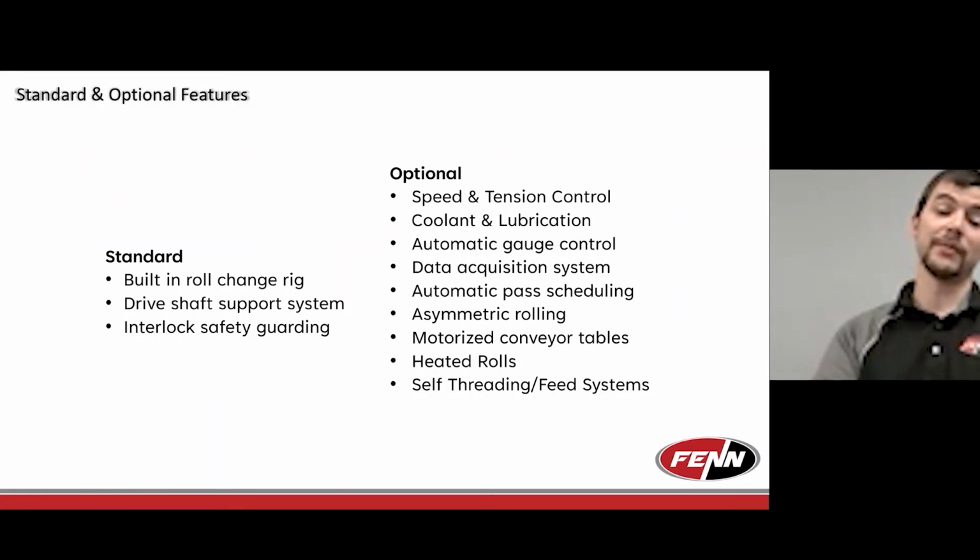So one of the other features I mentioned, obviously, that's very common in the continuous rolling side is gauge reading, where you can monitor your thickness on the fly and make automatic adjustments. So many applications nowadays where we're running continuous material, tolerance on the front and back side of the strip is huge. We provide gauging. We tie them into a control loop with the final stand in the line, where each gauge communicates with the front and rear adjustment, either the motors or the hydraulic cylinders, on that final stand in order to control the thickness and keep it within tolerance the whole time being run. And that's where it's very commonly used. So to skip around a bit to talk about some of the other things.